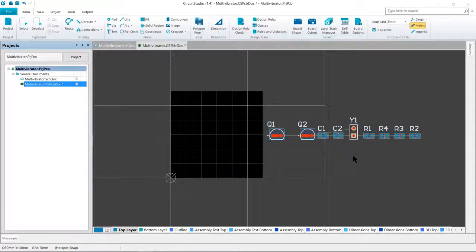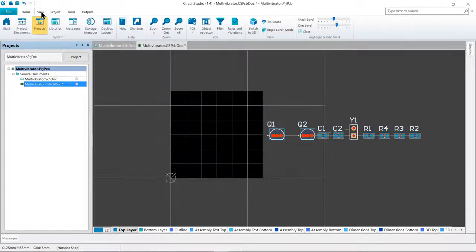Now, the display attributes of all layers are configured in the View Configurations dialog. To open this dialog, we can either go to the View tab, and under the Switch to 3D menu, we can click on this and go into View Configurations and bring up the View Configuration menu entry, or significantly easier, just click down here on the color box in the lower left of the workspace.